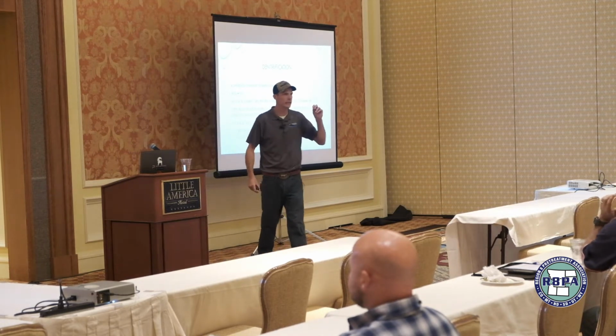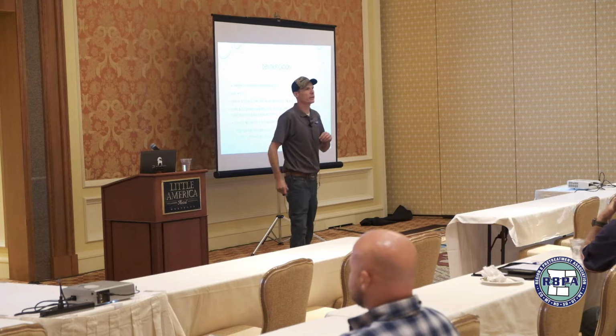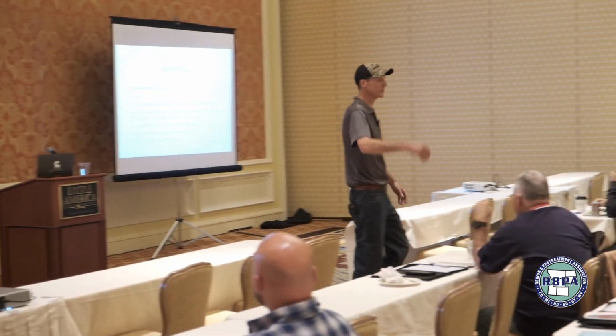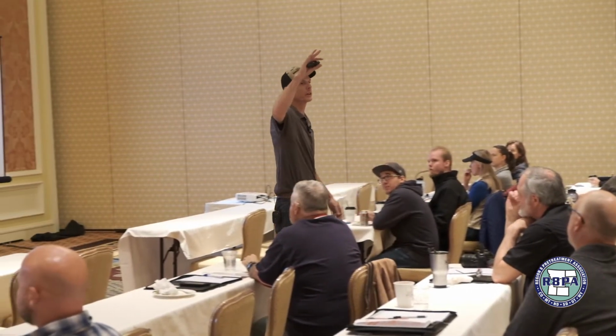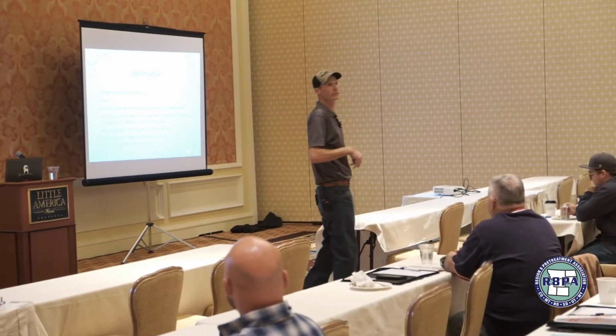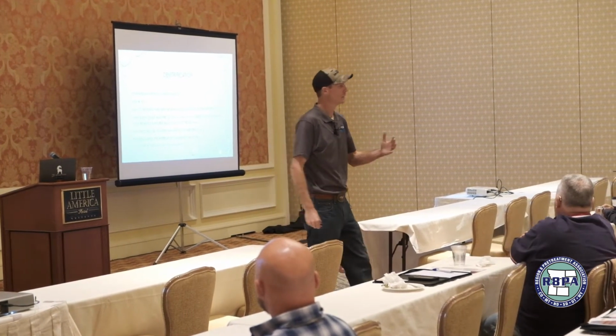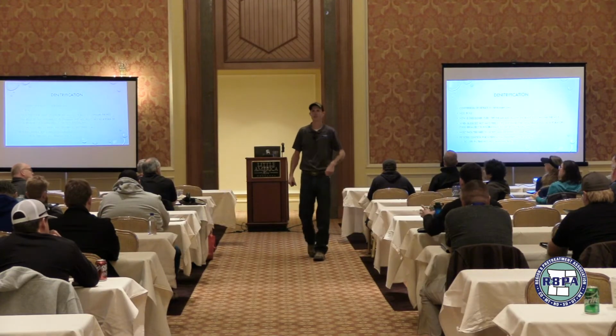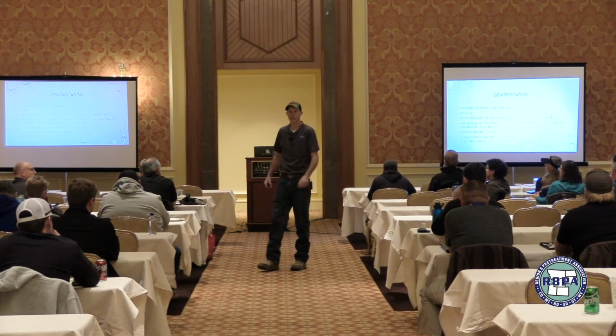So when I say they don't have enough free oxygen, we were talking about DO earlier, right? Everybody says, oh yeah, I got to have your DO at 2 to nitrify, down to 0 to denitrify. And I talked about ORP. So, anybody have an ORP probe or familiar with an ORP probe? Good. What level do I nitrify at? Greater than how many millivolts? Greater than 50 to 100 millivolts I can nitrify.